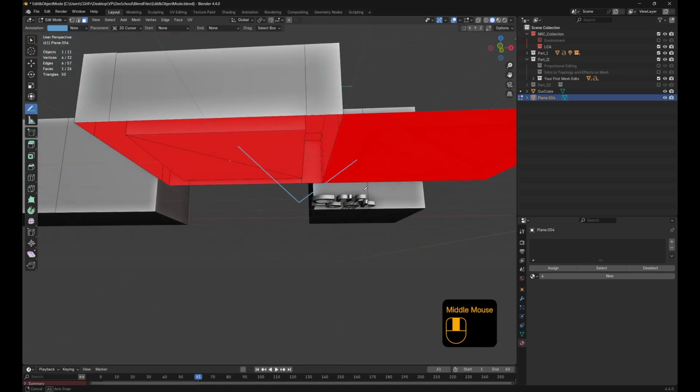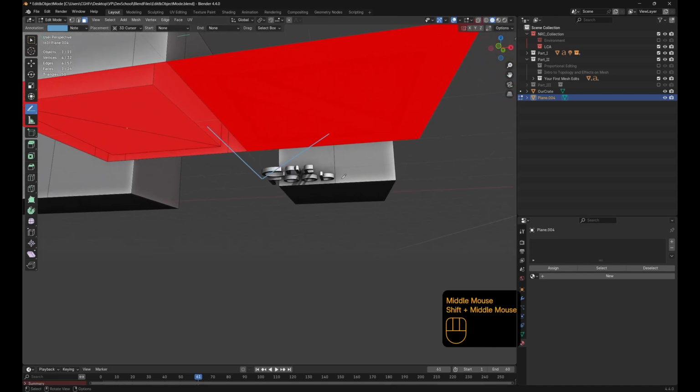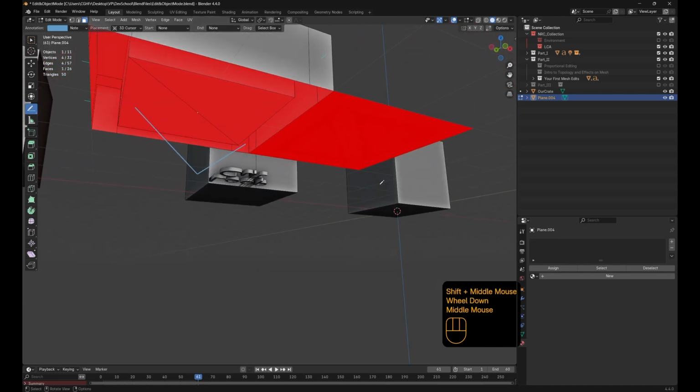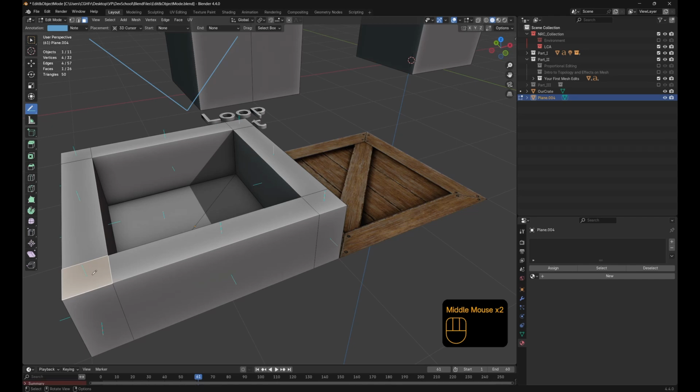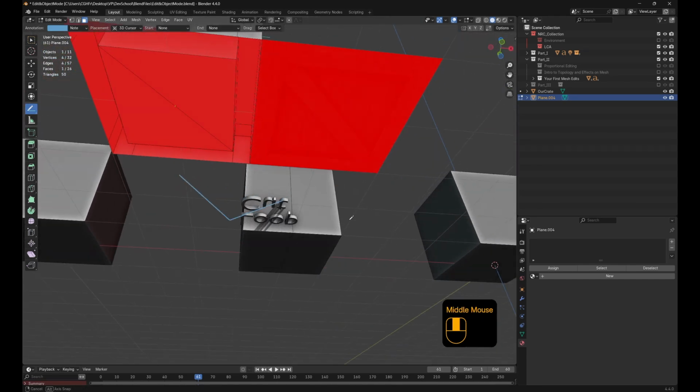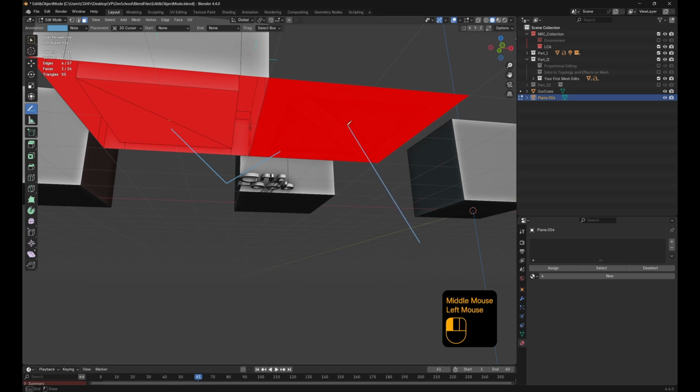We don't want to see any red, because what happens here is known as back face culling. If we've got a red face, so say this is our crate and this face here is red, when a bit of light hits it, instead of bouncing off it, the light will come along, see that the face is facing the wrong direction and presume that we want that, and the light will continue to go through. It won't bounce off, and we'll get some weirdness with our shading.